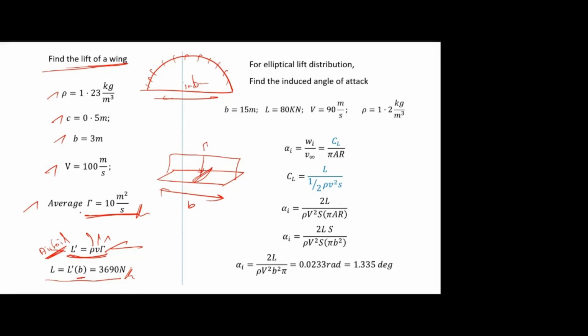So they mention circulation is constant. Normally, circulation will have some y term. Similarly for the ellipse, what you have found is gamma naught into 1 minus 4 y squared by b squared, like that we have got it, right. So here it is a gradient. Circulation is in terms of y, it will vary, but here they have given a constant value, which is average.